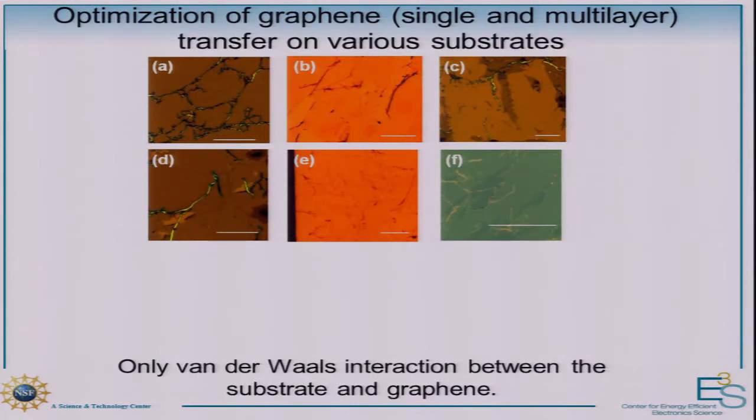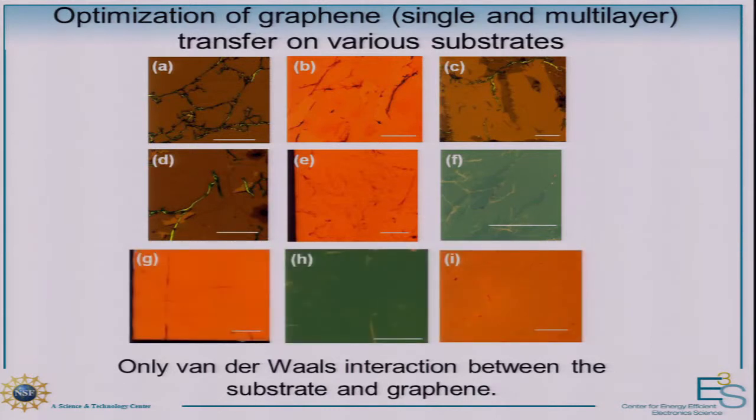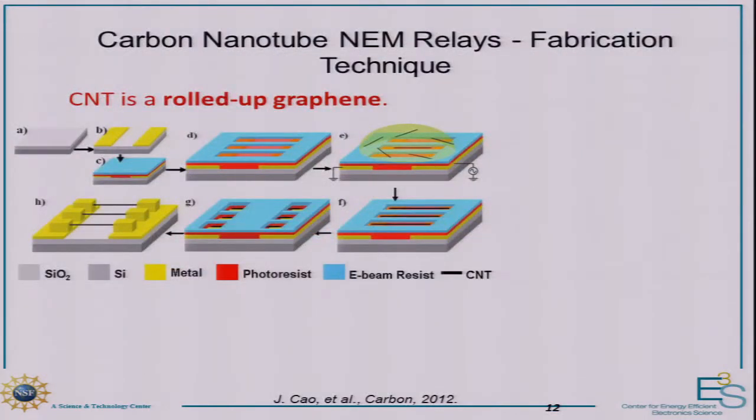So we tried different substrates: aluminum oxide, metals, with HMDS, plasma, silicon nitride. What we found out is there are several factors: the surface energy, the roughness, hydrophilicity, and hydrophobicity affect the adhesion. We know that in this sequence, metal, silicon nitride, aluminum oxide, and silicon dioxide, the graphene sticks better. And also HMDS doesn't work well because of weak interaction in the SAM. But the plasma works better for most surfaces except metal. It looks like plasma actually oxidizes the metal.